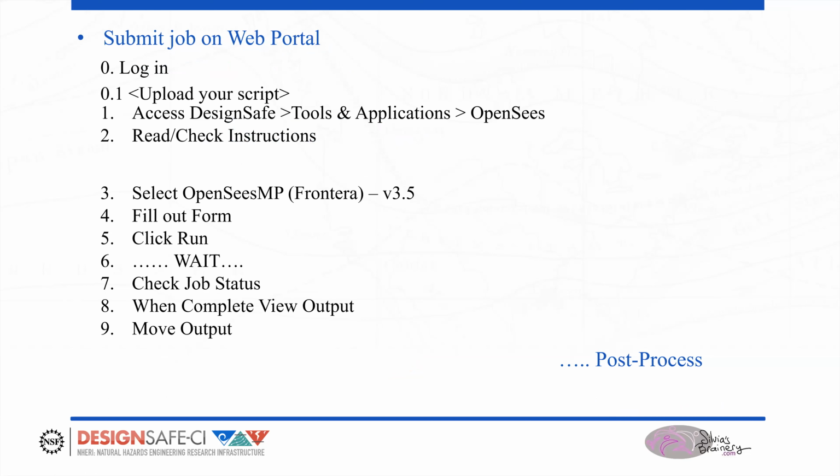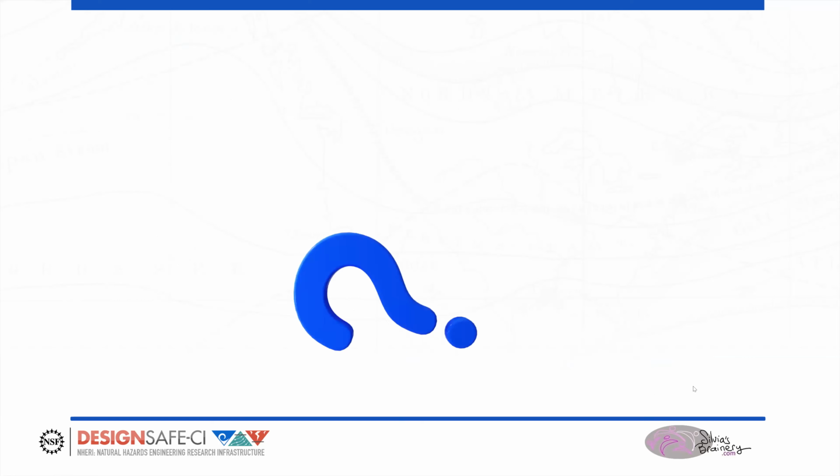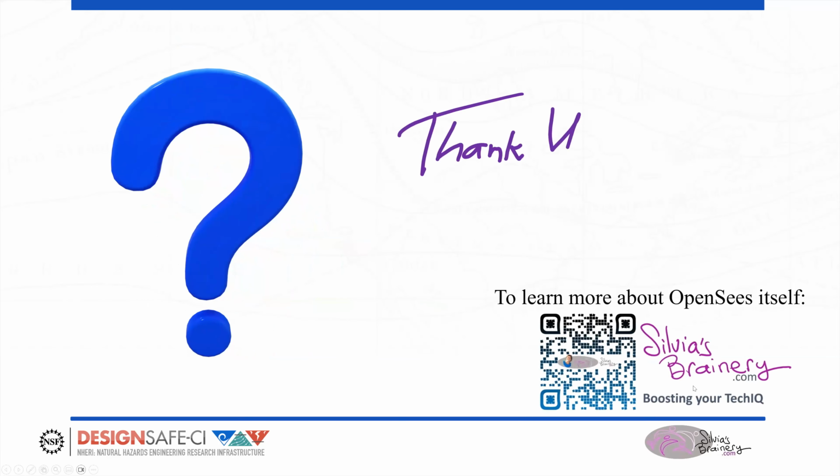And make sure you read in the documentation about multiple jobs, because it duplicates your input file, your folder and things. So you've got to be really careful about the data management, which I think is an excellent way of managing data. It just requires you to do a little bit of cleaning up at the end. And then you move your output when you're done and you post-process, okay?